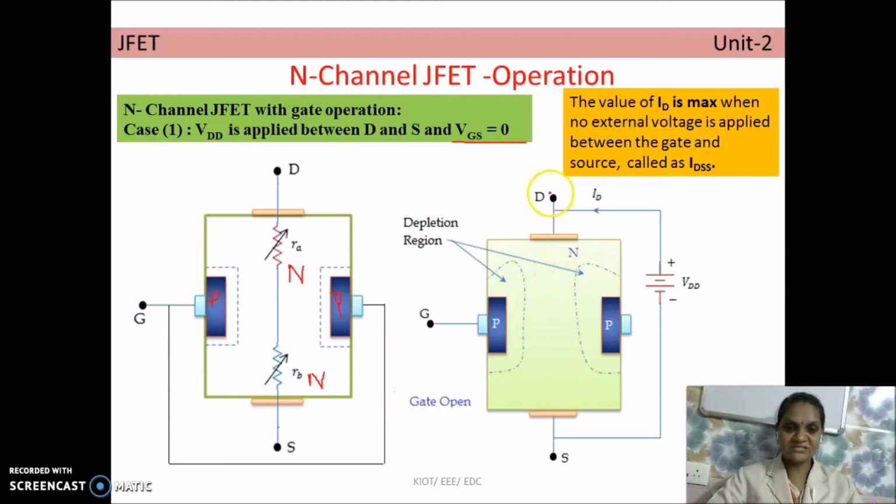The drain terminal is taken from N-type semiconductor material connected to the positive terminal, so this is reverse bias. And the other terminal of the N-type semiconductor bar is connected to negative. So we can say the source is in forward bias and the drain is in reverse bias.